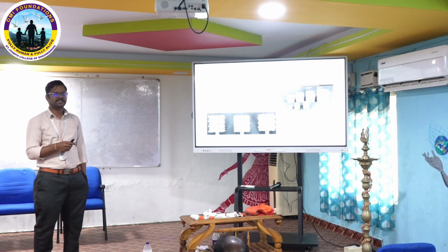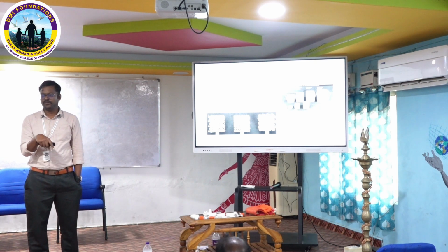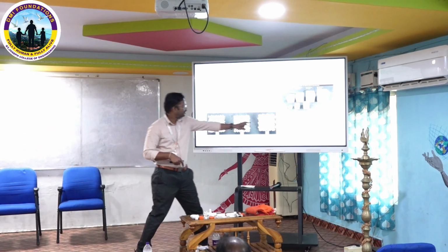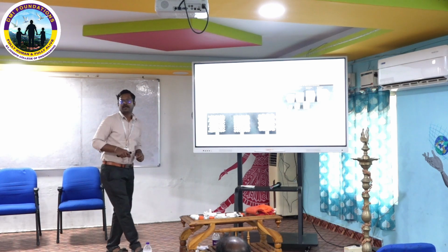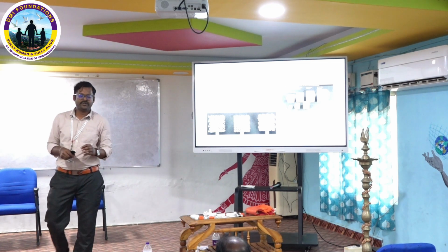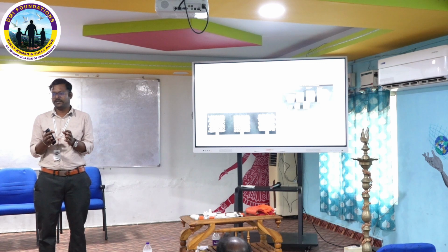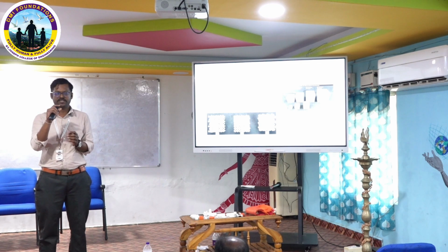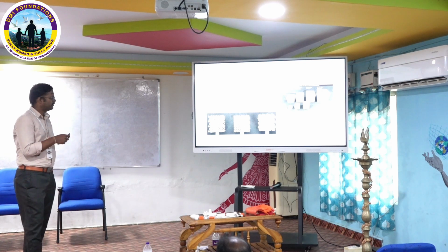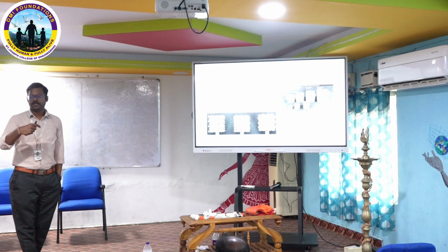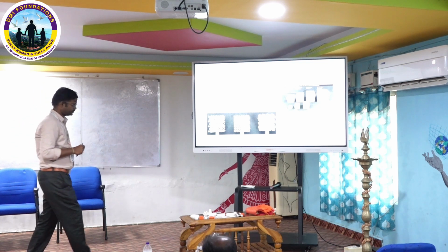Then cell size. Cell size is nothing but the size of the cube. This is a cube, and the dimensions x, y and z are the cell size. Commonly we use symmetric geometry only, that means cube-shaped lattice structure unit cells. So we have to think about what the size of x, y, z of the unit cell is.